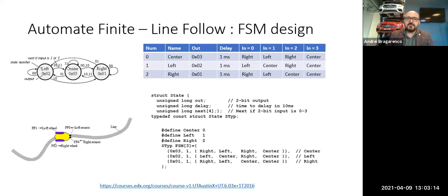So now the last problem, we can define the behavior of a follow line robot by defining that we have 2 sensors and 2 motors. And depending on which sensor is detecting the line, we can drive one or another. In the case we are going left or right, we are losing the line here. That means we are going there, and lost here. What that means? Stop this motor and drive this motor.